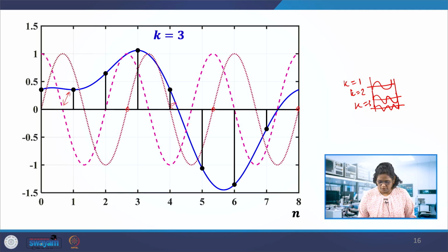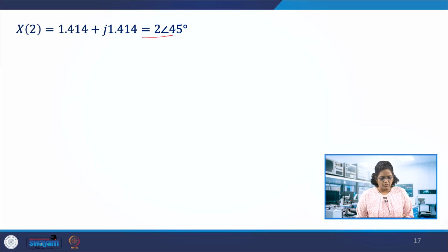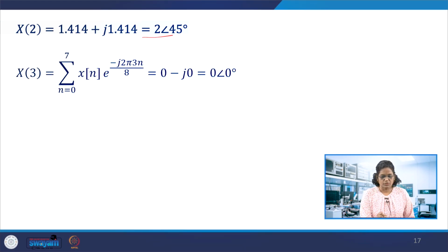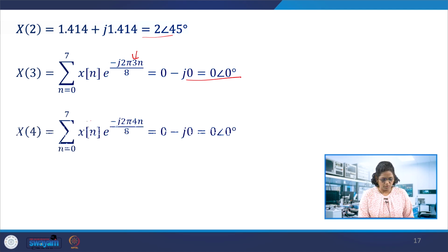So likewise, the sine and cos are correlated with the input signal to get the correlation coefficient, the correlated value. So X[2] shows some values here. And then X[3] similarly, if k equal to 3 and it results in 0, yes, there is no third harmonic in this. Fourth, k varying from 0 to N minus 1, so we vary up to 7 here.